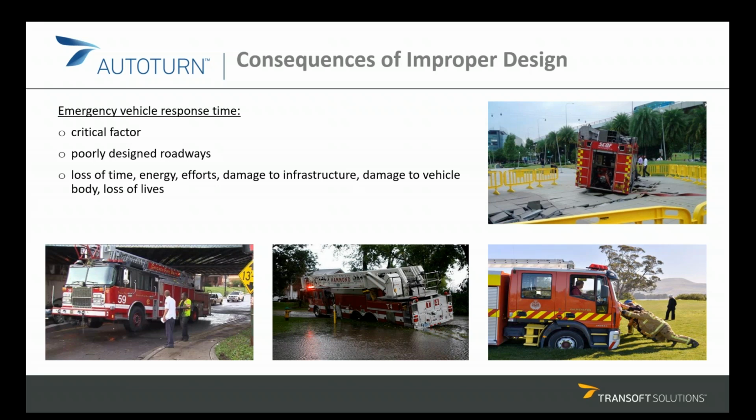The most common issues faced by emergency vehicles are ground clearance issues, overhead obstacles, body clearance issues, unstable terrains, and ladder deployment obstructions between the fire truck and the building. If roads and access lanes are designed properly to accommodate emergency vehicle access, it would help avoid unnecessary delays and the response time may be improved, which in turn benefits the efficiency as a whole and also results in fewer casualties.